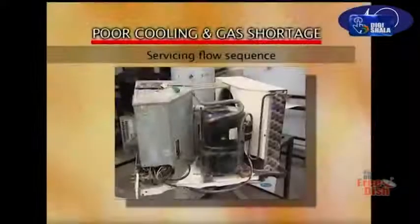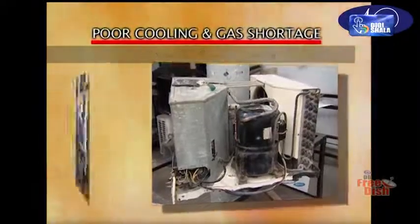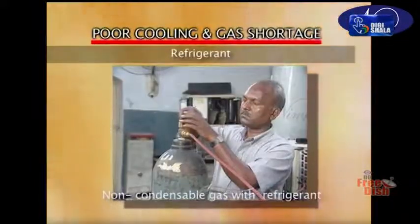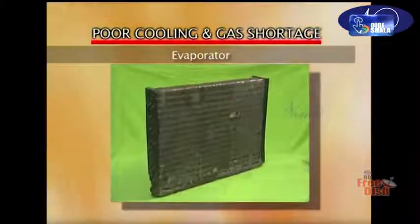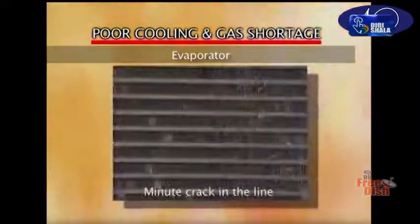Servicing flow sequence, poor cooling and gas shortage. Check the refrigerant for contamination of the refrigerant, non-condensable gases with the refrigerant, improper evacuation of the service cylinder. Check in the evaporator. There could be a minute leak in the evaporator coil outlet. There could be a minute crack in the line.